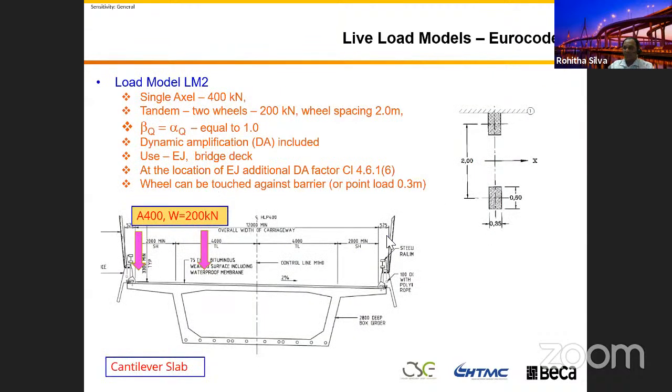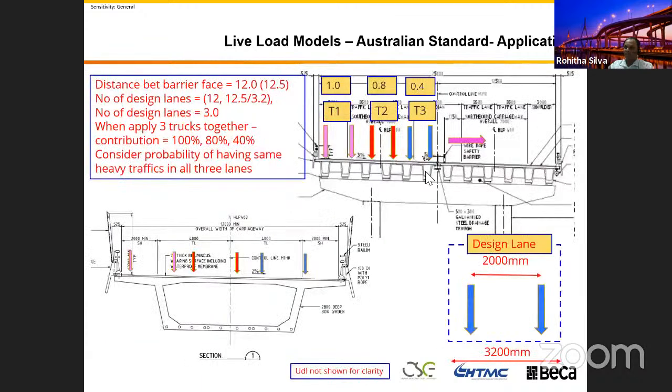As I explained in this slide, when you put the loading on this bridge, you should have your own imaginary bending moment diagram, and you need to mark those values, and you need to specify these load cases 1, 2, 3, 4, 5, 6. I don't want more than that. Then you check your results.